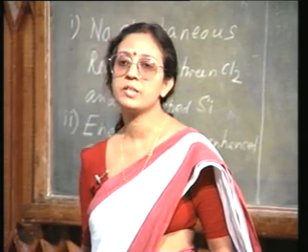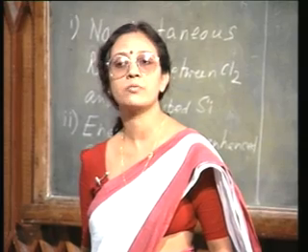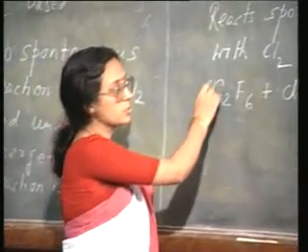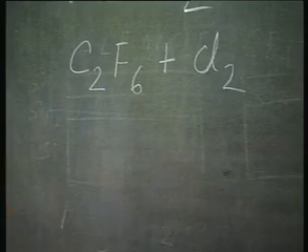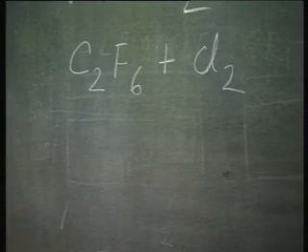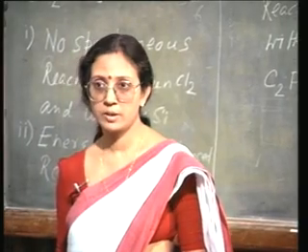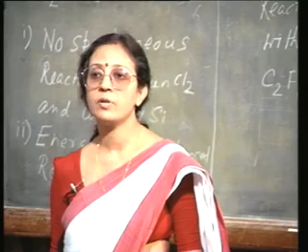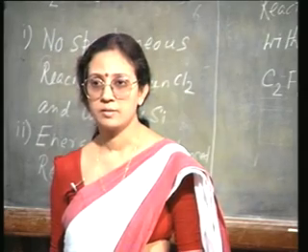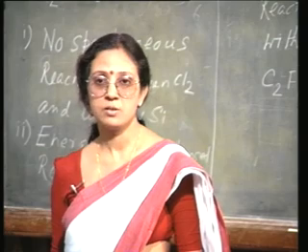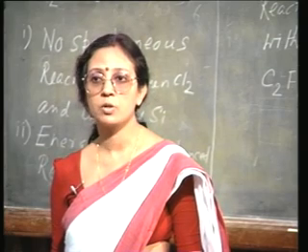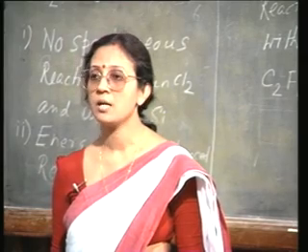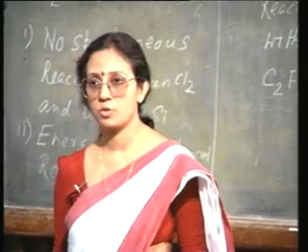However, here the feed gas composition has to be carefully monitored. That is, there should be sufficient C2F6 to form the inhibitor. Otherwise, you will get isotropic profile. So, you see, even here you have a lot of flexibility. By using the same feed gas with varying amount of relative percentage of chlorine and C2F6, you can get isotropic or anisotropic profile.